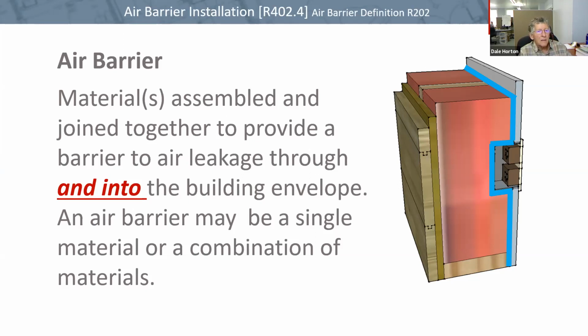But the Montana addition essentially was made to say that the air barrier needs to be on the inside of the insulation. The air barrier definition that IECC has does not specify, but years and years ago, DEQ suggested, and it was amended, so that I can currently say that the air barrier in a building in Montana is required to be on the interior.